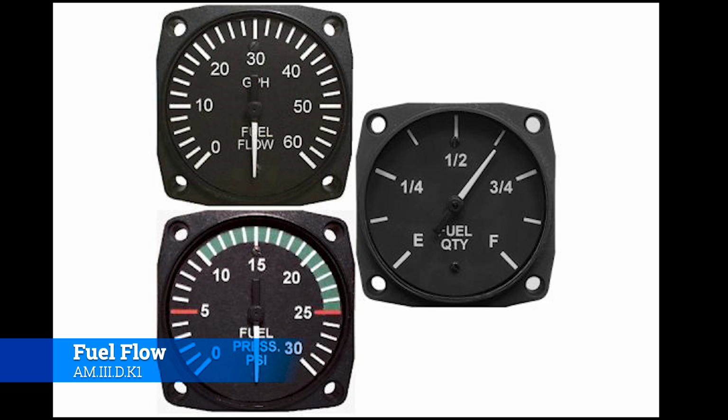Now, there is a chance that it overpressurizes, and you can over-rich the mixture that way, or simply flood the engine totally, and it won't fire either, because there's not enough air to actually ignite the amount of fuel that's in there. And even if it did, I don't know that you would want it to, because in that scenario, the engine may very well explode, because there's so much fuel in there, if it ever got going anyways. So either way, this is one of those engine health metrics that doesn't necessarily tell you everything, but it absolutely is the canary in the coal mine, and points you in the direction you want to go to know how to go about fixing it.